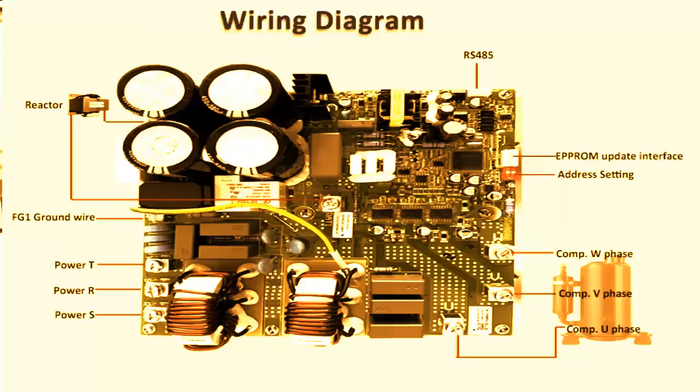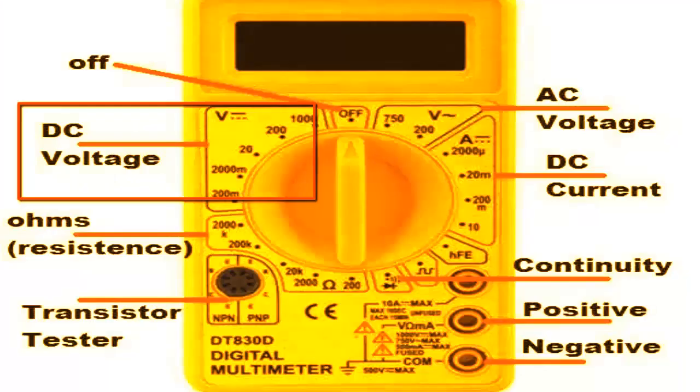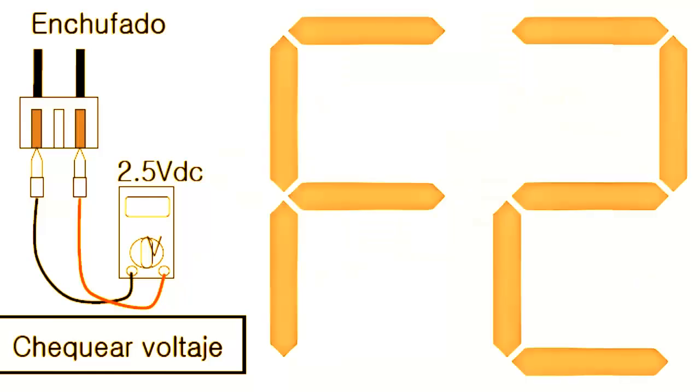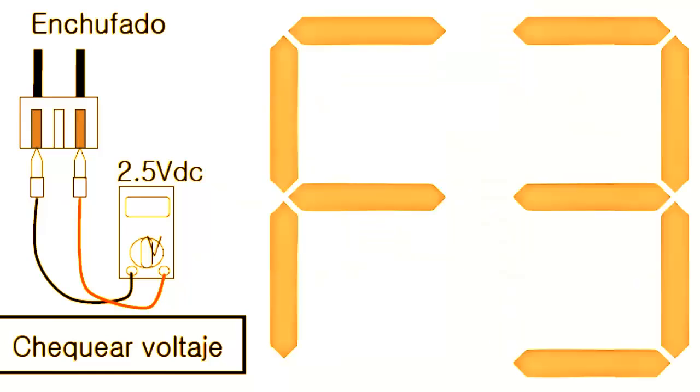8. If measurements indicate the sensor is electrically sound, focus the study on the board's power supply to the sensor. 9. Connect the sensor, turn on the equipment, and, using the multimeter on the direct current voltage scale, measure if the sensor's electrical supply is correctly around 2.5 volts. Otherwise, the damage could be in the external board.